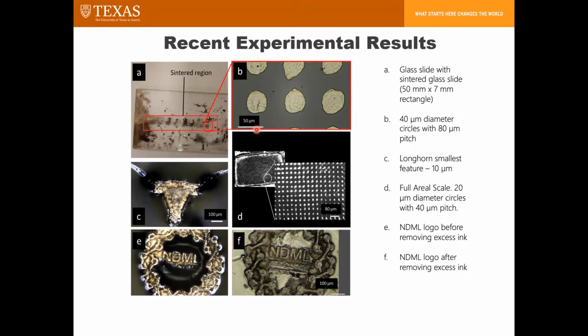And so one of the major challenges to creating these nice looking parts is understanding how the heat spreads during this process. Currently, one of the challenges is actually we're seeing parts that are outside of the laser exposure that are either partially sintered or fully sintered. And that's just due to the heat transfer from the surrounding. So Georgina will be speaking a little bit more about the simulation side of that to kind of understand this problem.